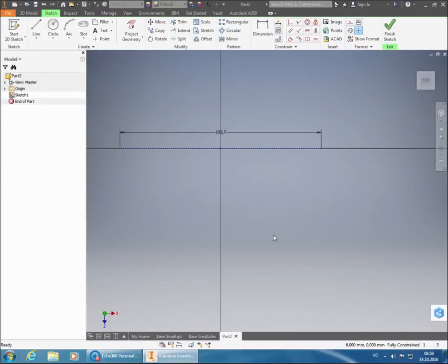We're going to have this line start at the end of the vertical line here and go upwards, and then it's going to go into a radius curve and attach to the other side. So the way we're going to do this is to, first off, start in this end and start creating the vertical line. So we go into the line option, click that one, then I'm going to attach it to the end here.